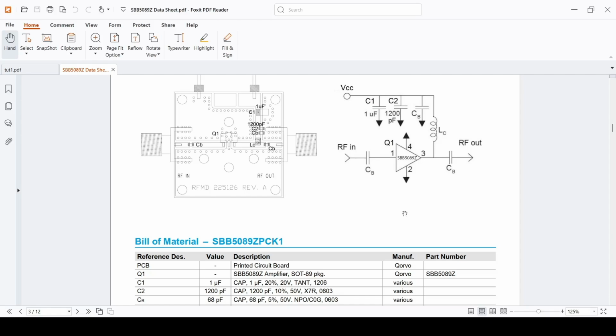So now that we know the basics, we know that one of the things that we need to take care of is the impedance matching. When we want to design the circuit, first we want to have the ability to simulate this. What we can do is that usually the IC providers provide us with an S parameter file of their amplifiers.